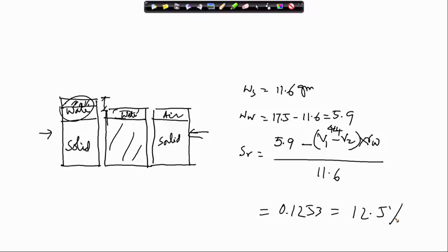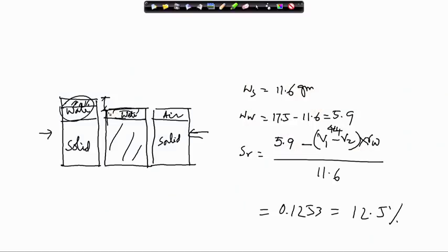What is the definition of this? This one has to understand very carefully: when we are drying, the soil will reduce in volume, but there is a minimum volume it reaches and it will be saturated. That is the condition. You have to find the water content, and that water content is the shrinkage limit. So, this is the minimum volume, and it is also saturated, this much water is filled up, and in the other condition, this is the same minimum volume, but there is no water. So, I have to find out, corresponding to this volume, what is the water present in the soil. This is the step in the calculation we have to remember.